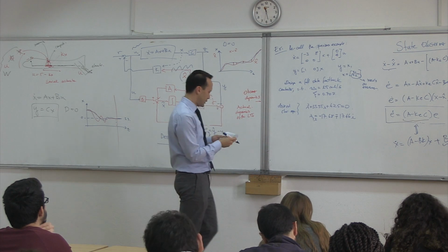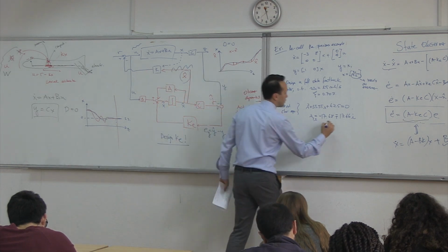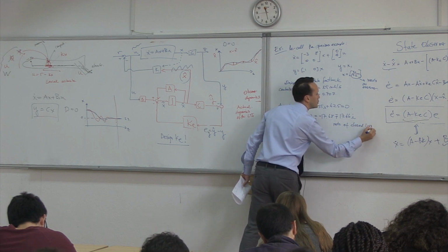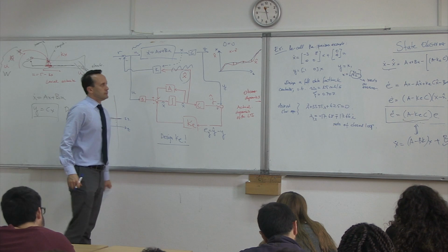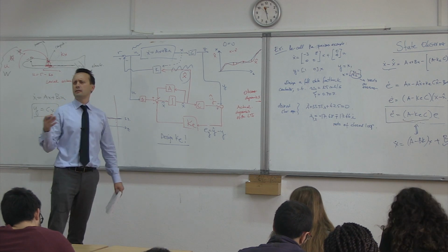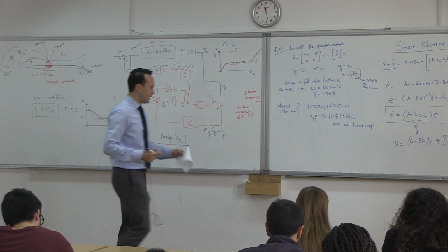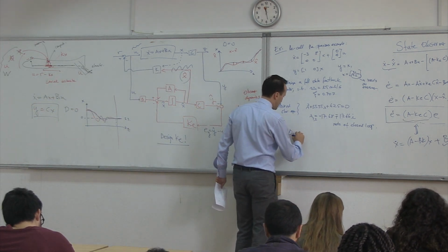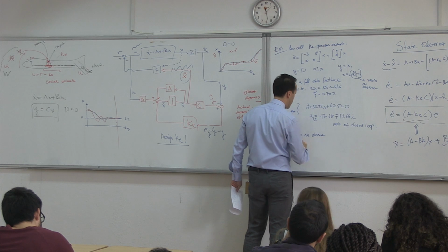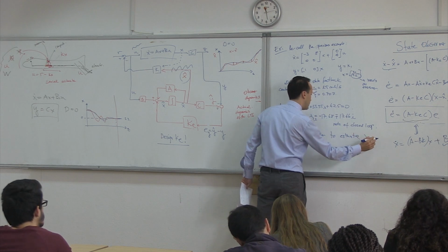These were the desired characteristic equation and the roots of the closed loop. And we have designed a feedback gain for this. I think it was something like 16 and 9, as I remember. So we designed that. Our goal now is to design an observer to estimate x.